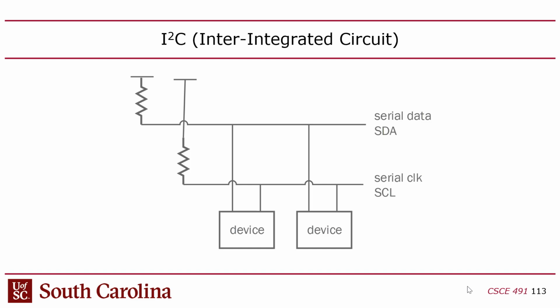I2C is more of a strict standard. So with I2C, these names are almost always SDA and SCL. SDA stands for serial data, SCL stands for serial clock. So basically, if you compare it to SPI, SPI has S clock and I2C has SCL. That's the equivalent signal. Okay, so they're both synchronous buses.